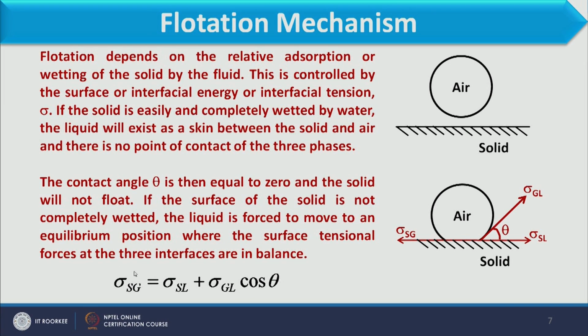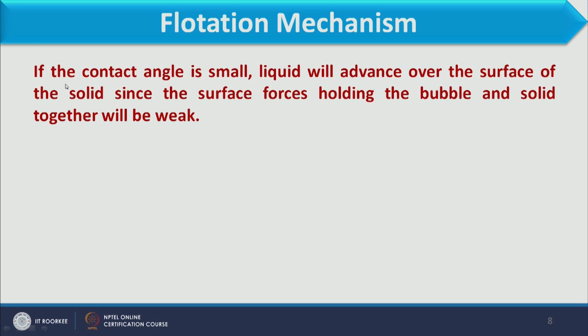So, this is basically the balance of forces, and these forces are caused due to surface tension. Here you see theta is an important factor as far as bubble formation is concerned. If bubble formation is large, theta will also be large, and if theta is large, it means floatability should be enhanced. If the contact angle is small, liquid will advance over the surface of the solid, since the surface forces holding the bubble and liquid together will be weak.